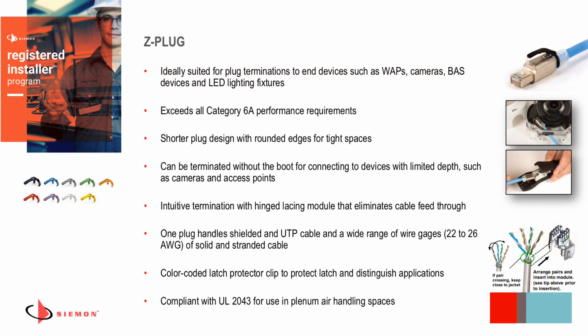Now, we had talked earlier about the modular plug terminated link, or MPTL, and the Z-Plug is Siemon's solution for terminating those MPTLs. Z-Plug was designed from day one to terminate to the devices that we've noted, such as wireless access points, security cameras, and PoE lighting fixtures, things of that nature, but at a high performance level. It supports termination of 5E, 6, as well as 6A fully shielded cables, even category 7A S/FTP style cable.